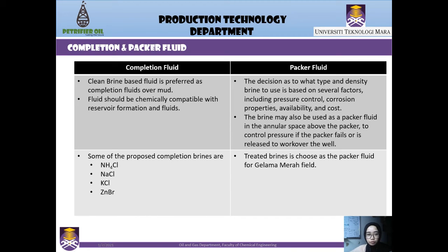For the completion fluid, it is preferred to use the clean brine compared to mud due to salt's ability to go into the solution rather than having suspended solids that may settle after a long period of time. This clean brine is also chemically compatible with the reservoir formation and fluid for this well.